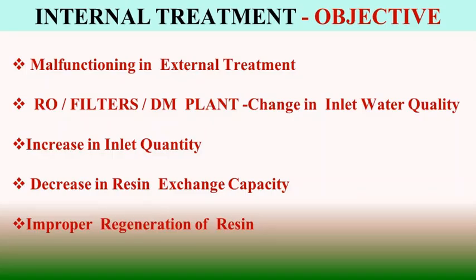So far we have discussed the various pre-treatment processes. Now we are going to discuss the post-treatment processes, or internal processes. The purpose of an internal process is to react with the feedwater hardness and prevent it from precipitating on the boiler metal as scale, and to condition any suspended matter that can create hardness, sludge or iron oxide in the boiler tubular parts or metallic parts through which the water stream is flowing.